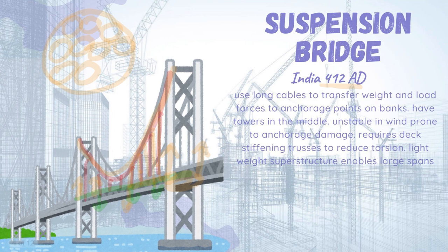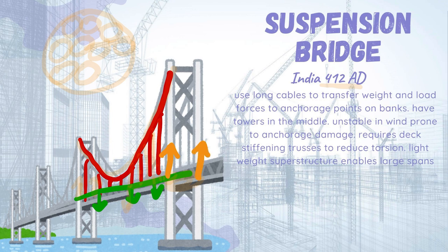Suspension bridges. So suspension bridges are characterised by their cables, which are used to support the weight of the deck. So the cables help to distribute the weight force of the deck. So if we have the deck, it's got a weight force which is quite substantial, especially when you load it. And if you just have the weight being supported by the pillars, so if it's only being supported here, that causes a significant moment force at these points.